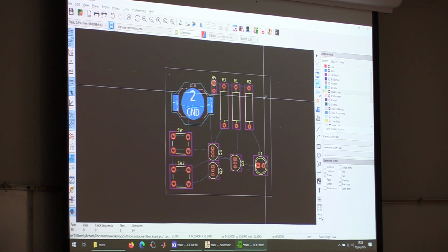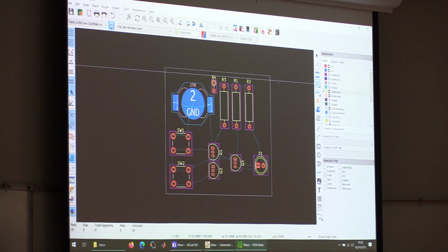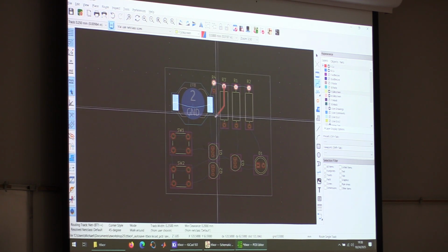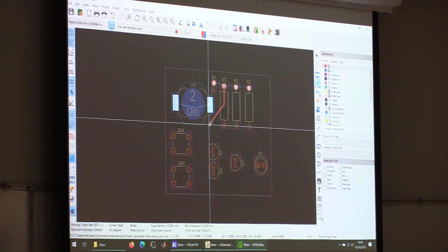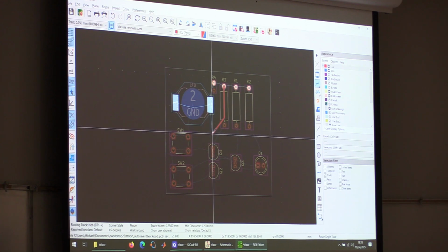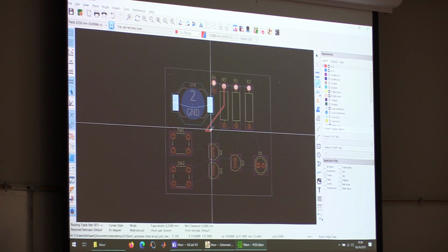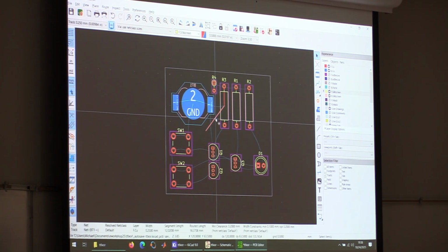Is there a way to flip which direction goes? Sometimes when you try to draw it at an angle, it's down and diagonal. Usually, are you talking just the trace? Yeah. The way it auto routes traces can be a little bit finicky. Even I have issues with that. So what I'll do sometimes is I will place it, and then I'll click on it again and manually move it around. So you can play with that a little bit too.